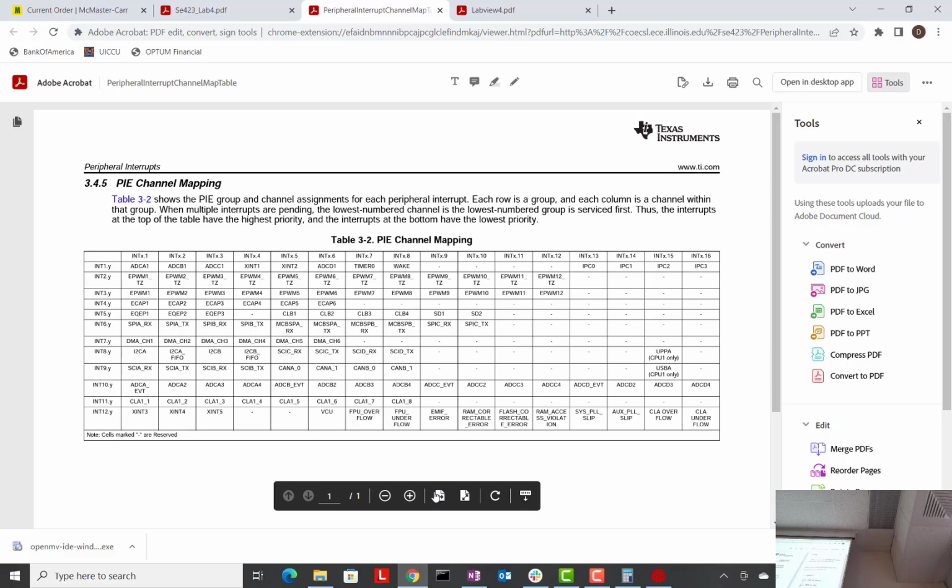I used to teach the SWIs in this class, but I steered away from it this semester because of the following. Remember how we have the option to put our code in RAM or in Flash? Well, when you run with this operating system, it's so big that it only fits in Flash. So you can't set as many breakpoints. It takes a little longer to download your code to the robot. So I chose not to go that route, and came up with my own little way of creating this thing